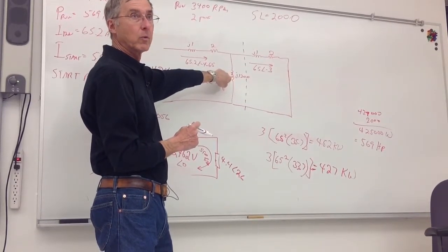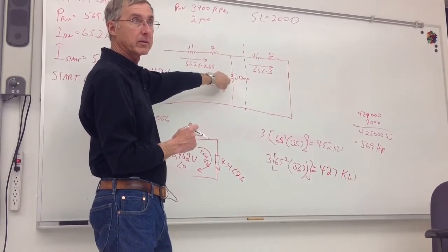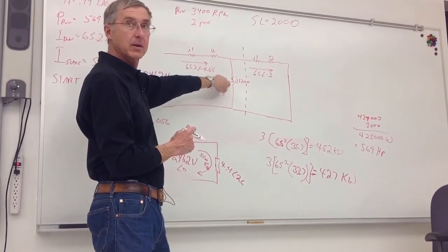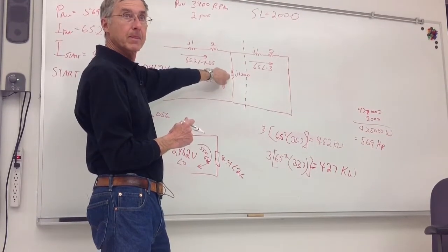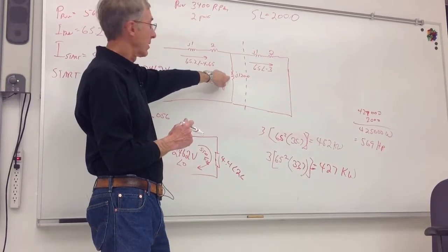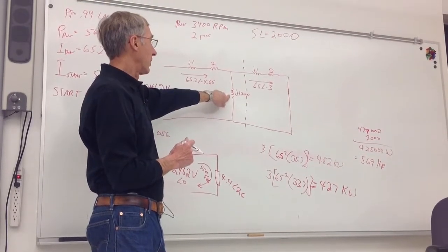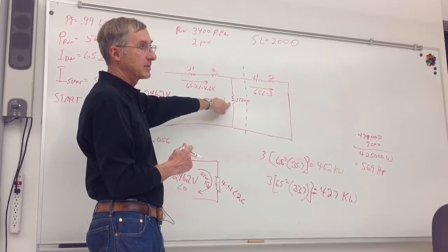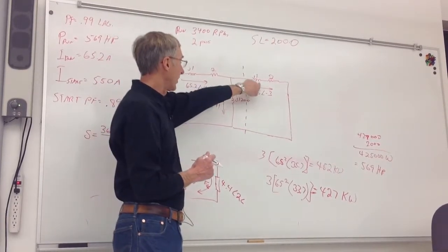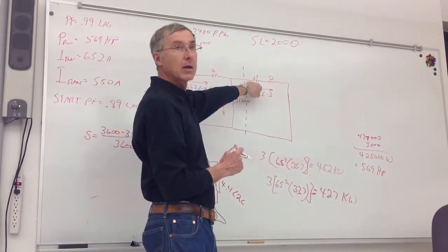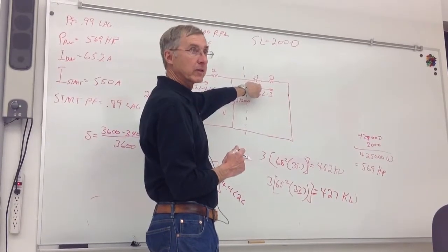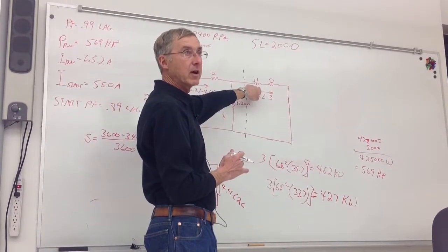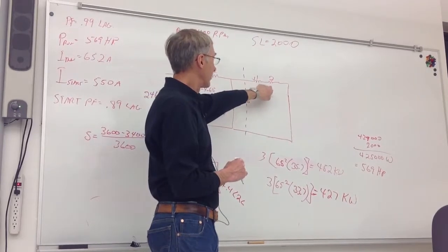Okay, what is this a model of? This piece. The amount of current it takes to set up the magnetic field. Okay, it's going to give me the equivalent reactive losses due to magnetization. What's this? The rotor. That's going to be modeling the reactive losses in the rotor. What's this?